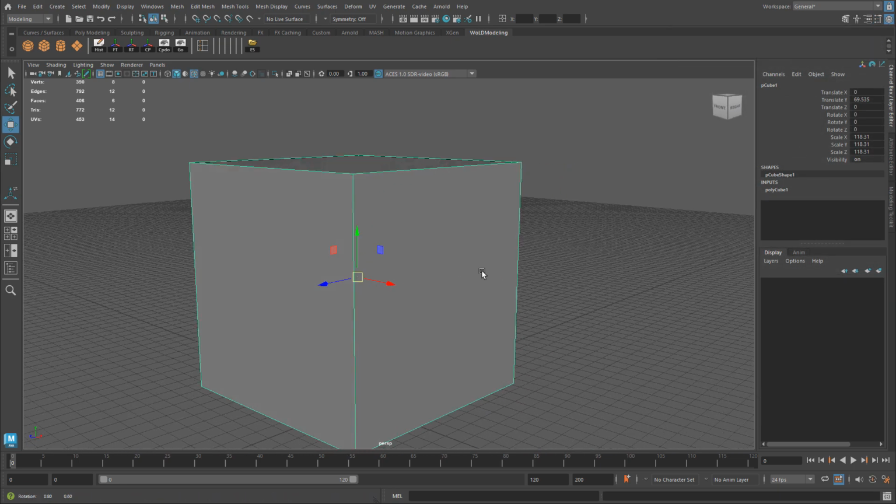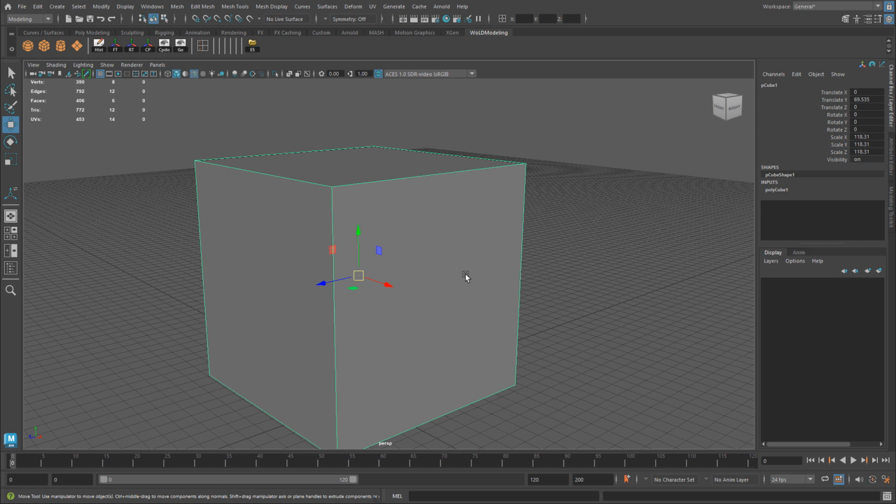And then whenever you need to modify the pivot point, here's the proper way to snap that pivot point to the 3 parts of an object, either to a vertex, edge, or to the grid. So I'm going to hold down D, and to snap my pivot point to a grid, I'm going to hold down X, and then middle mouse click and drag, not on the gizmo itself, but on the grid where I want to snap that pivot point to. And middle mouse click and drag it, not left mouse click, but middle mouse click.